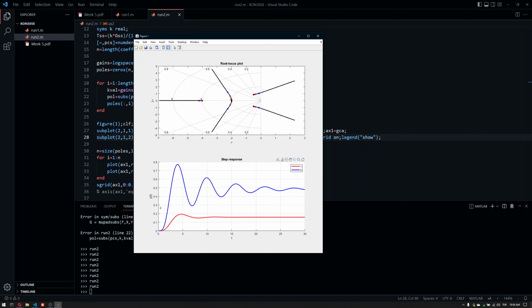Now, if we increase the gain a little bit for this system, we have higher oscillations, and the reason for that is we have lower friction. As you can see, the damping ratio is lower, the friction is lower, therefore the oscillations increase. If this is a mechanical system, this would be the comment I could make about it: it has low friction, it is oscillating too much, and you can also see that it is a slower settling down, or kind of transitioning into the steady state way later.